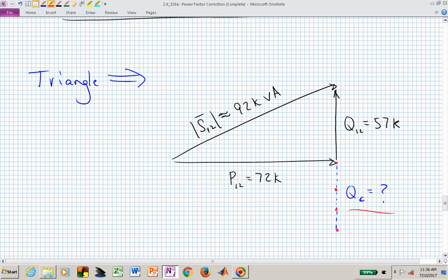And that will then really allow us to reduce the demand on the source and reduce the current that is being requested from those two loads, loads 1 and 2. They haven't changed at all, and they're still able to receive what they need, but now that capacitor is providing this exchange of power closer to the loads and allowing the supply to not have to be as large as in the past.